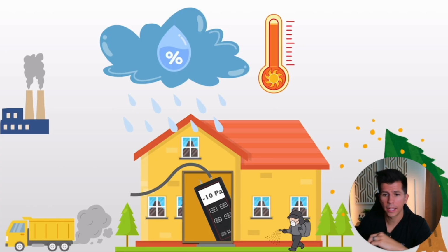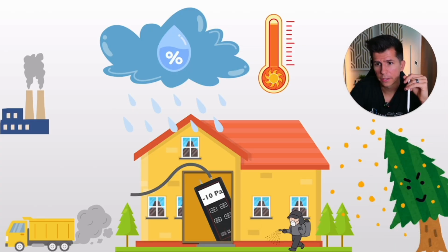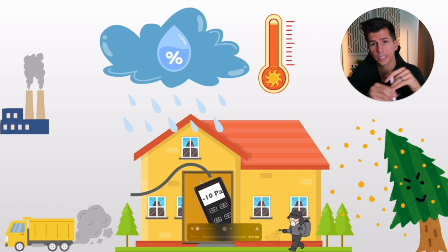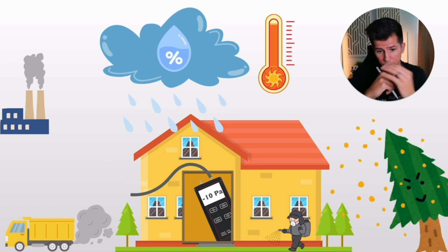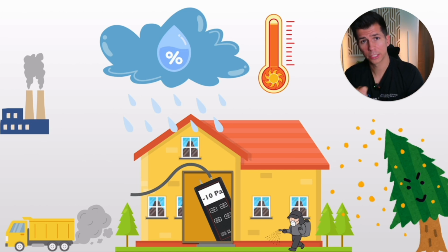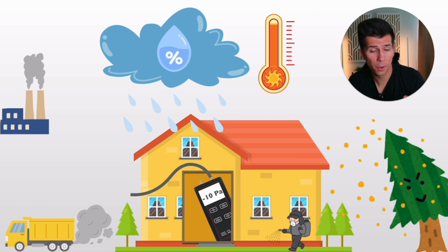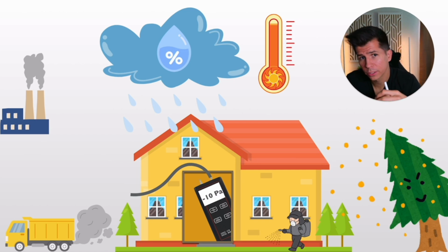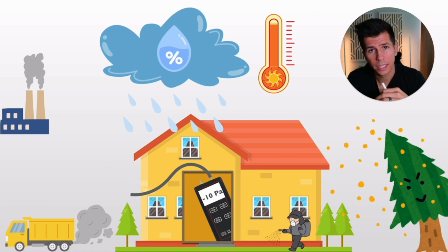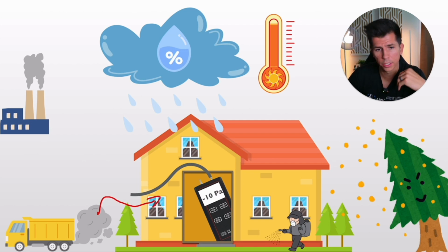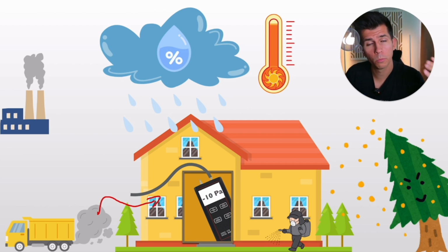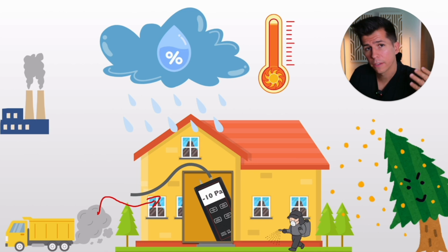Now, let's take a look at something like this. We're dealing with lots of pollutants outside, lots of pollutants. So now just imagine that you have your manometer and you're measuring the pressure difference between inside the entire home and outdoors. So maybe the house is -10 pascals in relationship to outdoors. Well, what do we have to worry about outdoors? Well, we have a lot of pollutants from cars, which, you know, most of them are what we call PM 2.5, very small particles, less than 2.5 microns.